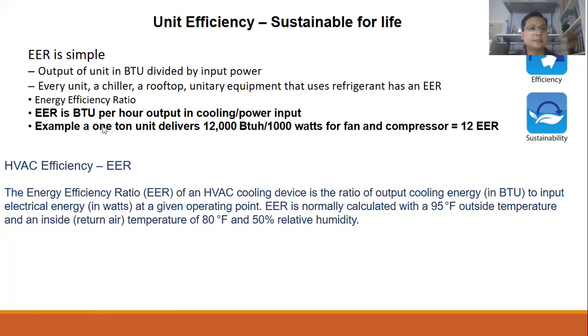We can use EER when the outdoor temperature is 95 degrees Fahrenheit, or around 35 degrees Celsius. The temperature inside the room should be 80 degrees Fahrenheit, and the relative humidity should be 50%.